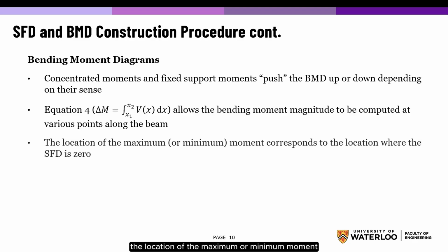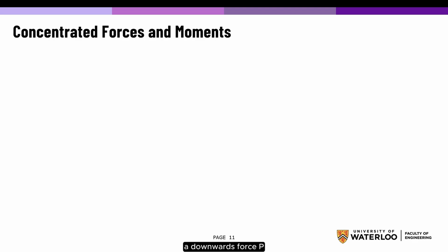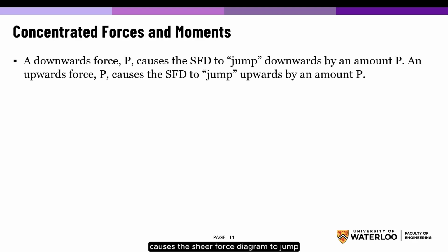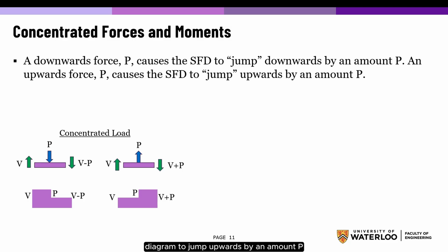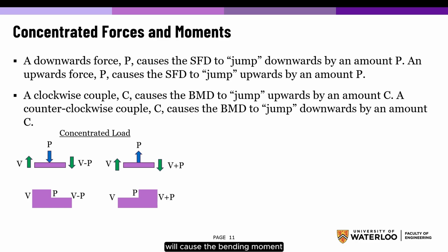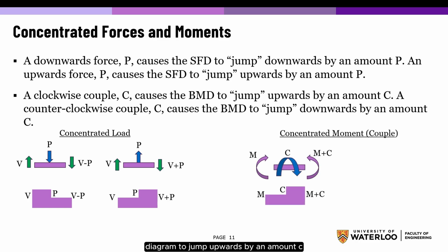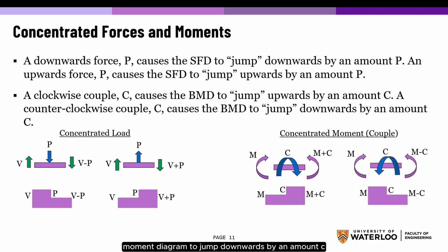The location of the maximum or minimum moment corresponds to the location where the shear force diagram is zero. Concentrated forces and moments. A downwards force P causes the shear force diagram to jump downwards by an amount P. An upwards force P will cause the shear force diagram to jump upwards by an amount P. A clockwise couple C will cause the bending moment diagram to jump upwards by an amount C. A counterclockwise couple C will cause the bending moment diagram to jump downwards by an amount C.